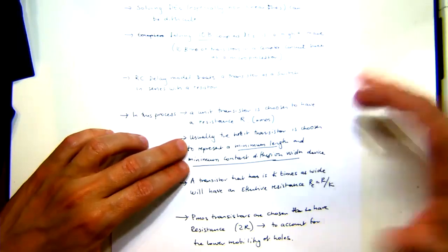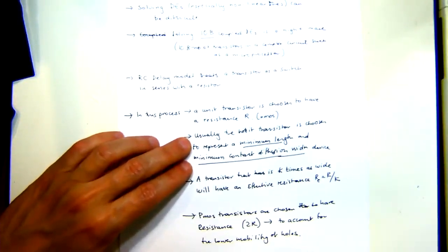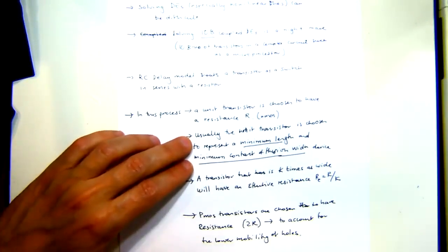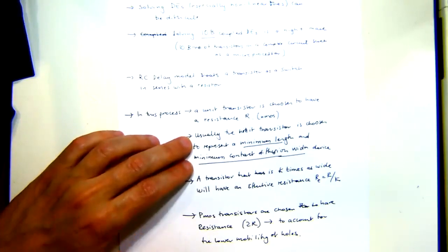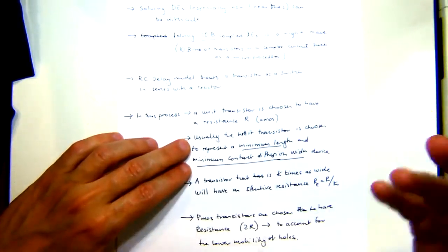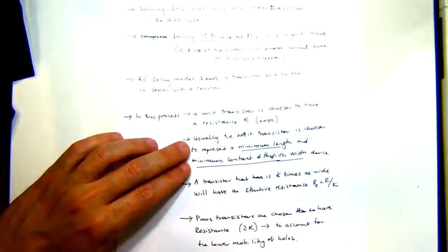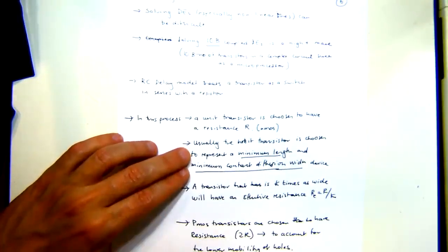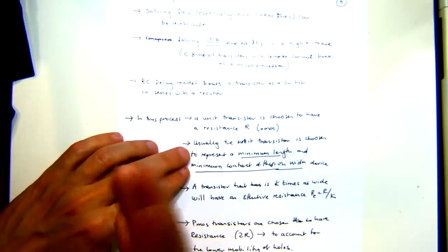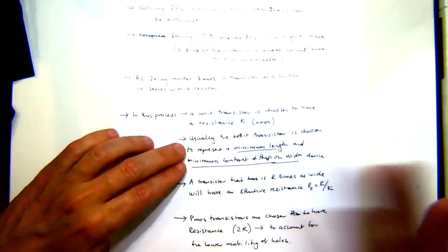Okay, so it's 65 nanometers. Usually when someone tells you 130 nanometer or 7 nanometer, what it means is the minimum feature length, and if you think about it, that's the minimum gate length. It gets a little bit tricky towards 7 nanometers because it's not actually 7 nanometers, it's a little bit larger, but they do some tricks that make it look like 7 nanometers.